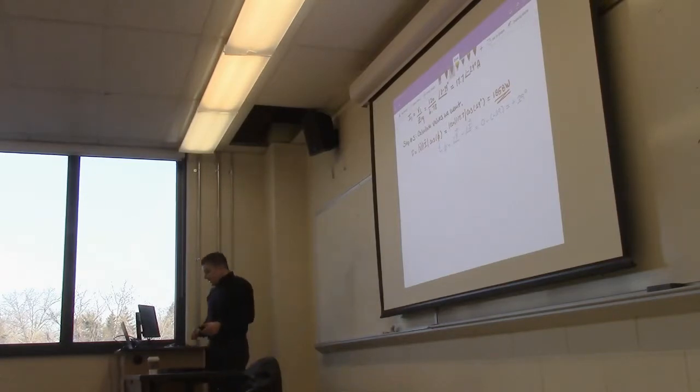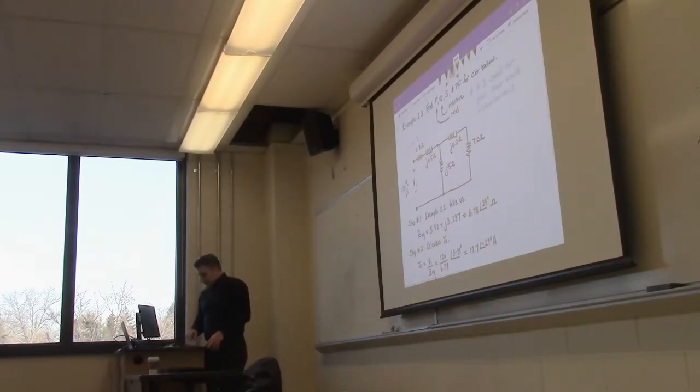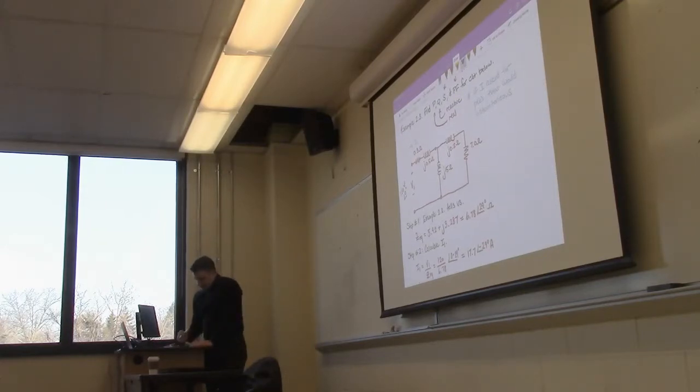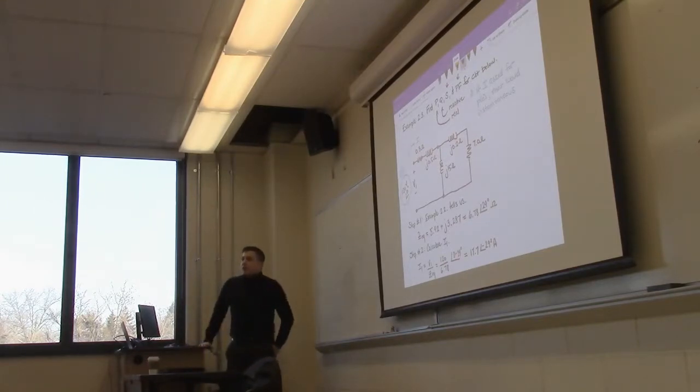And so you can see here, in this one, this is our reference with regard to phase. So everything is based off of that. If you were to do these measurements using an oscilloscope and you're trying to calculate phase, you would be looking specifically at the difference in time between the zero crossing of the current or other voltage waveforms, because they're not all going to be 0, and the zero crossing of that.